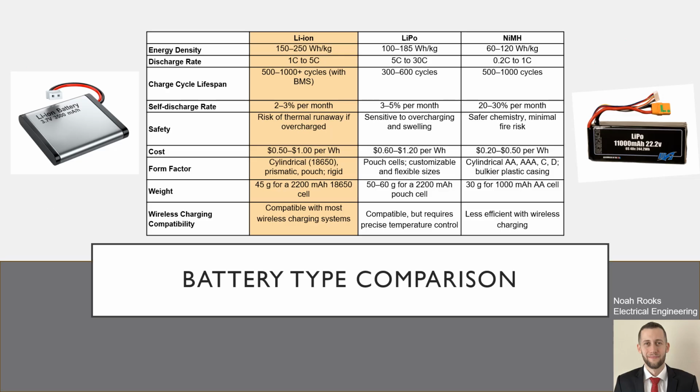Being a mobile monitoring sentry, the battery is one of the most important decisions. Initially, we considered using a nickel metal hydride battery. However, after further evaluation, we chose lithium-ion batteries instead. These are significantly smaller and more power dense, which is essential for our compact design. They also offer much more compatibility with wireless charging, which is one of our key stretch goals.